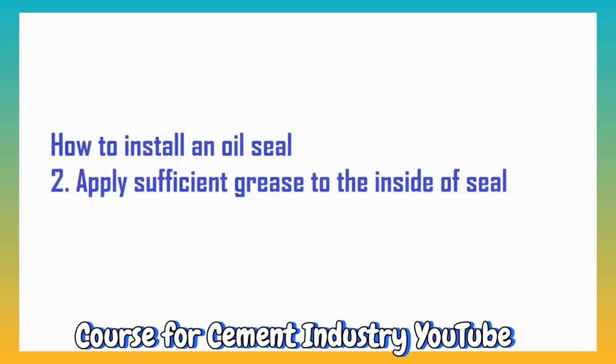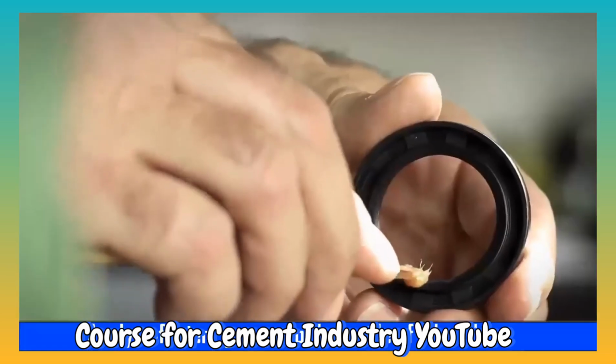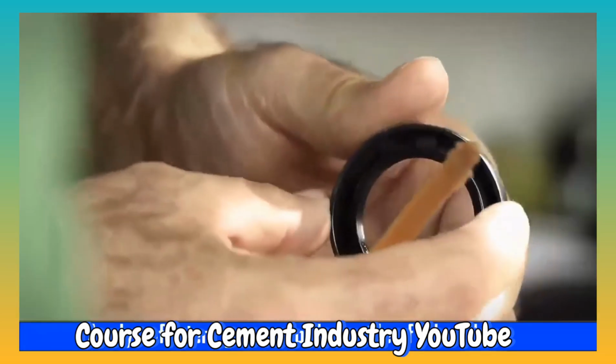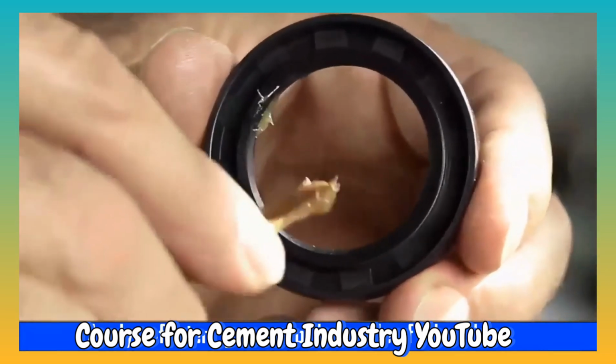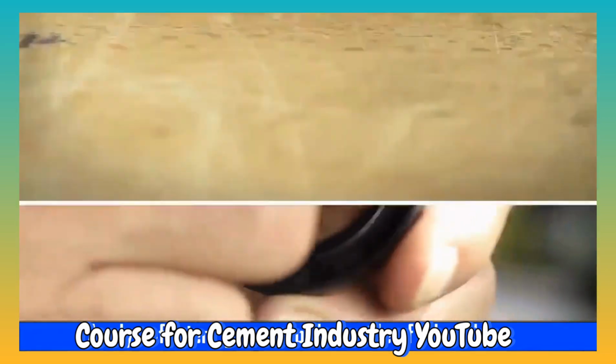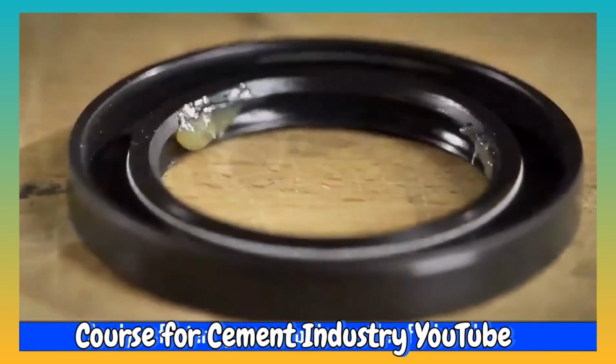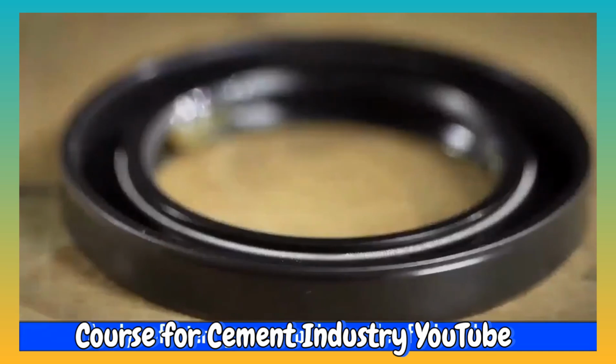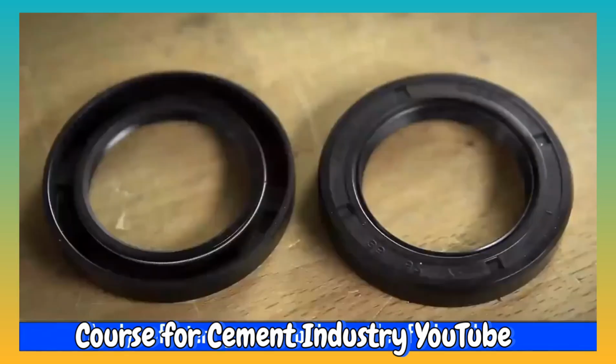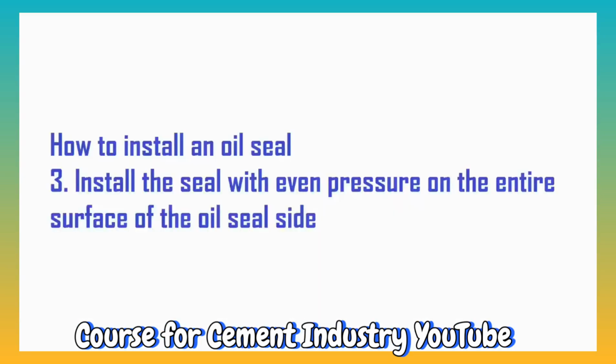Apply sufficient grease to the inside of the seal before installing the seal. Install the seal with even pressure on the entire surface of the oil seal side.